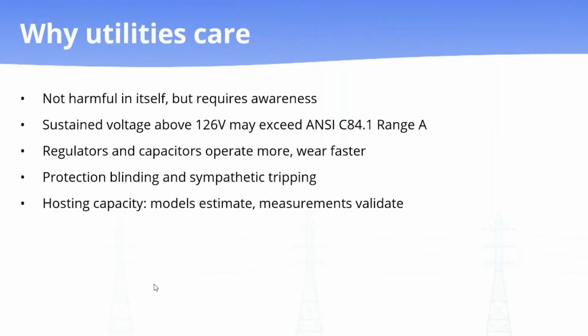Reverse power flow isn't inherently harmful. Modern planning increasingly assumes some bidirectional flow, and a feeder that exports for a couple of hours a day isn't in trouble. Problems come when export becomes frequent, widespread, or large on infrastructure set up for one direction. The question is how much, how often, and what it's doing.